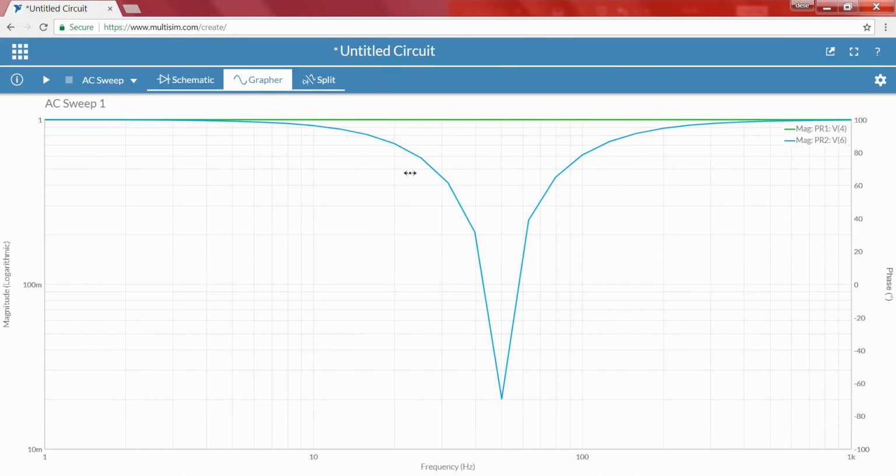Now, how do we understand, since in most cases we may not have a function or the frequency spectrum to visualize our filter? What we can do is analyze the cutoff frequency of the filter by looking into the time domain. That is what we were visualizing in our previous experiments too. Now, how do we do that?